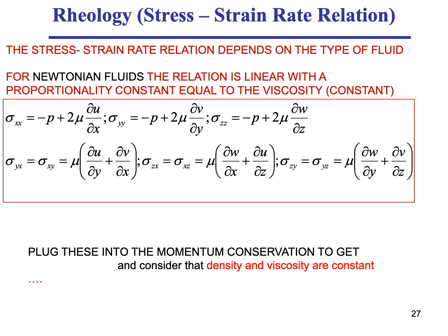So we have three normal stresses: sigma xx, sigma yy, and sigma zz. These are the stresses perpendicular to the respective faces. And we'll see that pressure is compressive and perpendicular. Because it's compressive, pointing towards the face, it has a negative sign. If you take the normal vector to the face, it's pointing outwards, and the pressure is compressive. In each of those terms, we have a pressure component of the normal stress, and a viscous component of the normal stress, just because it has a mu, or viscosity, in front of it.